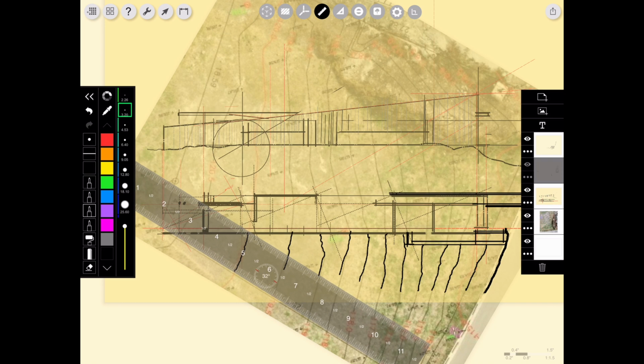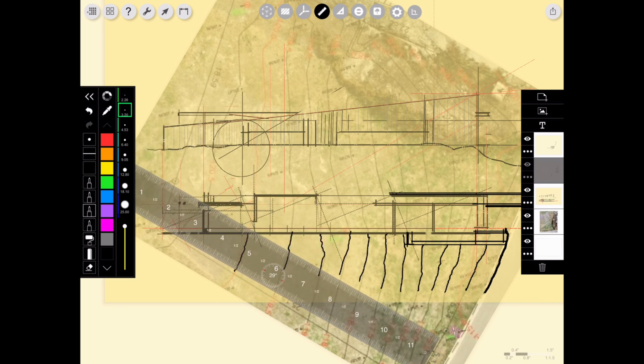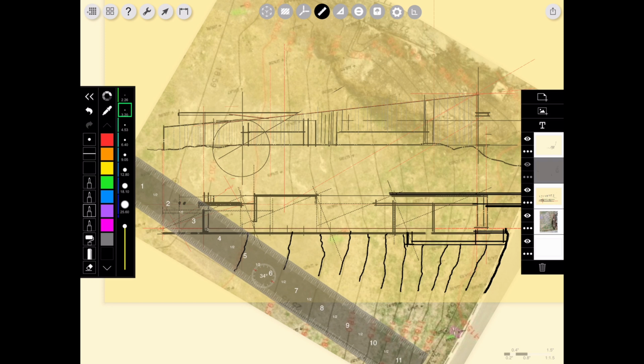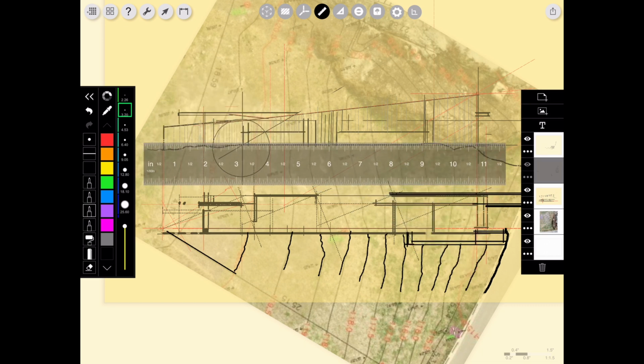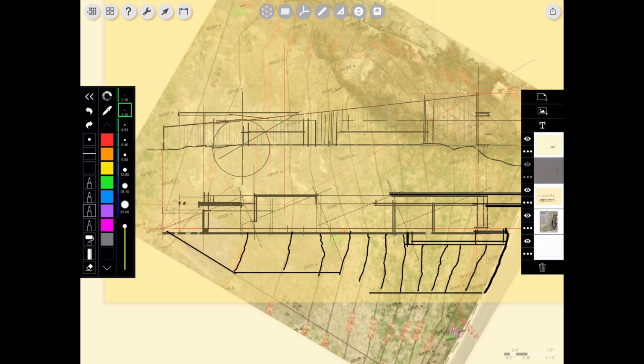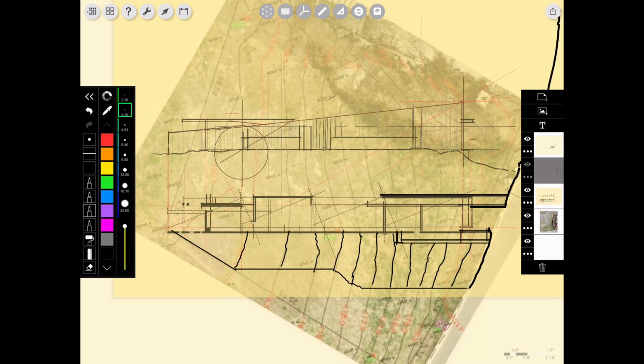When working to try to define a boundary edge, I highly recommend using Morpholio's Super Ruler tool. That way you can have the ruler enabled and not necessarily have to have the ruler in place in order to draw a straight line. And you can always in the settings toggle off the angle snap, and that way you can draw a straight line in any direction. It becomes really quick and easy to get nice crisp edges and boundaries and contours. Specifically contour lines as opposed to contours in terms of the site plan.